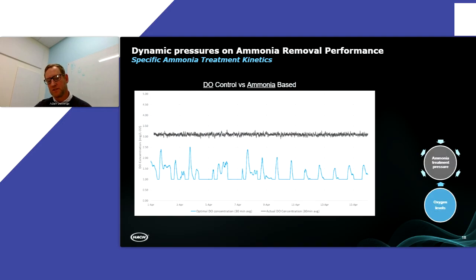We don't usually do it today, but we have in the past been really traditional about how we do dissolved oxygen, providing dissolved oxygen to our organisms. And you can see that black line. This is a really common way that we've done this traditionally, and lots of facilities still run this way, where the dissolved oxygen is controlled based on a fixed set point. So we're just trying to maintain a fixed set point.